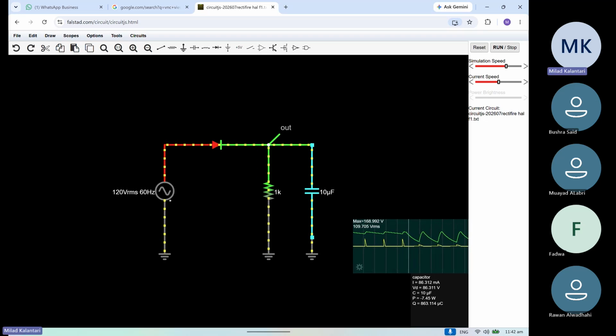It is RC, right? For these values, how much is it? 10 millisecond, right? So it means that if it has passed maybe four tau, four time constants, then the cap will be totally discharged. After 40 milliseconds, this cap will be almost totally discharged, right?